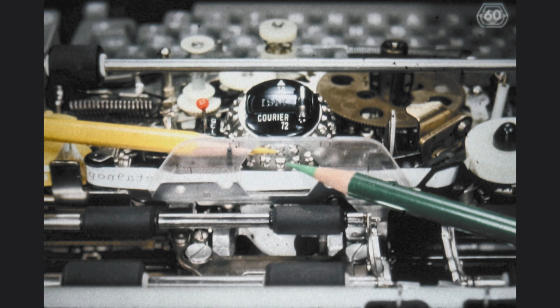IBM covers the whole subject under the label character selection. Let us begin with the tilt mechanism. The purpose of the tilt mechanism is to rotate the element in a vertical plane, meaning that the top of the element rotates toward the front during the selection movement and toward the rear during the restoring movement. The purpose of the rotate mechanism is to turn the element within any one of the tilt planes, or positions, selected by the tilt mechanism. This means that the front of the element turns toward the right or toward the left.